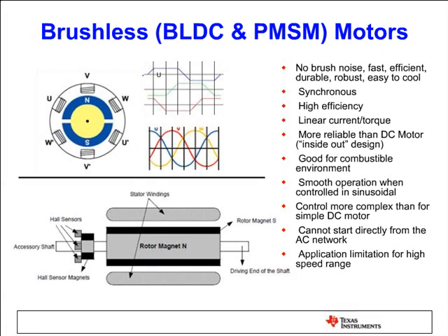So there are two types of PM motors, basically. I'm talking about the very popular ones, the BLDC type of motor and the PMSM type of motor. Now, here in this slide, the picture belongs to a BLDC type of motor. As you see, there are magnets on the rotor, the rotating part, and phase windings around the stator. Now, the difference between BLDC and PMSM type of motors: first of all, they both use permanent magnets, and they are pretty much the same, except the stator structure.